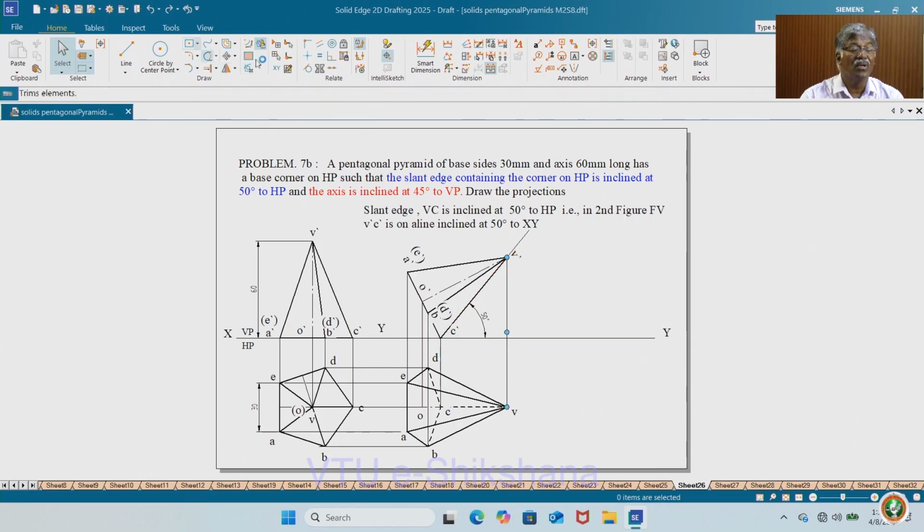You know how to use the rotate option, then project it. So the same concept: the farthest item from you is C, C is not visible, and any lines connecting to C are not visible, then all remaining lines are visible. This is how you can complete the visible and invisible lines, the concept of visibility is over.